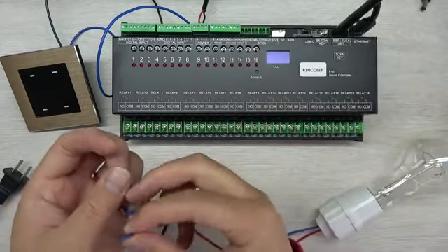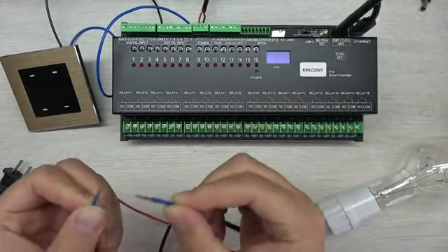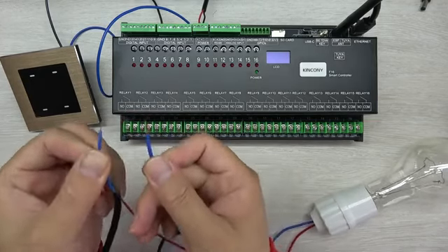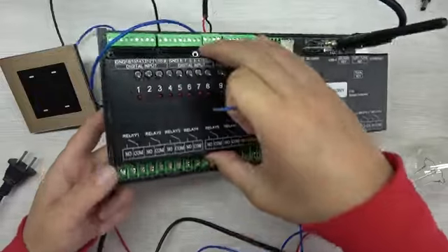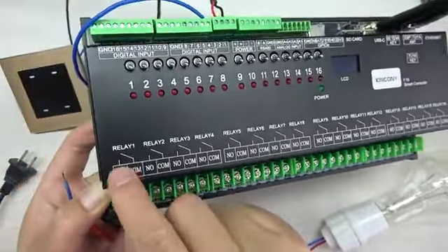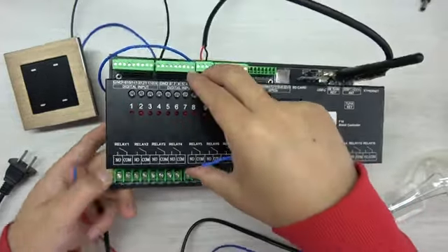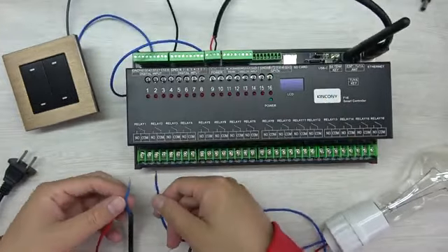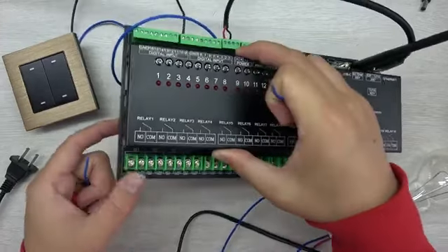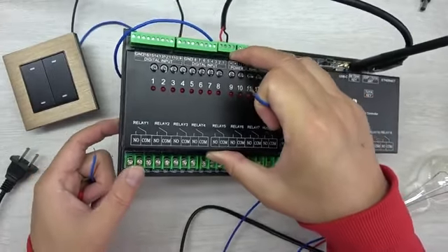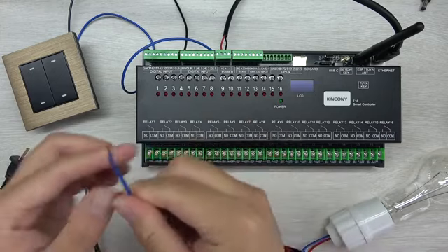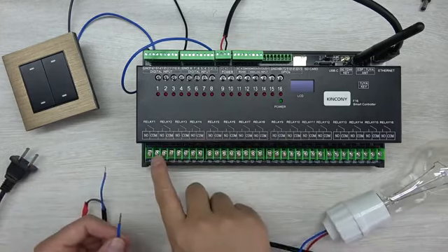So just this way, have a switch, have a relay. We have a relay to control these two cables. So I will choose this relay 1 and work as a switch. You can see this is a switch. So I will connect these two cables with the common and the normal open. And anyway, you can use any one. For example, you can use this cable and connect with this COM.